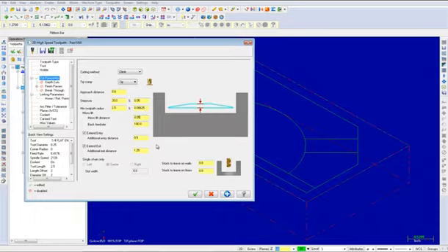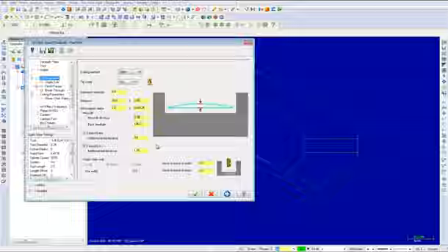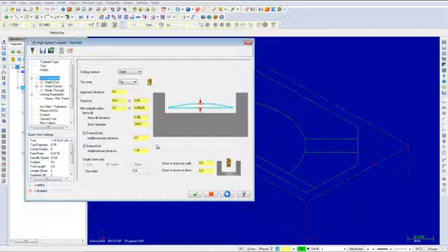Micro lifts are slight lifts that help clear chips and minimize excessive tool heating. Back feed rate controls the speed of the back feed movement of the tool. This allows 3D arcs between cuts to have a different feed rate than the rest of the toolpath, which can help reduce cycle time. And finally, Extend Entry Exit allows you to adjust the initial and final tool engagement with the material. From here, select the depth cuts.